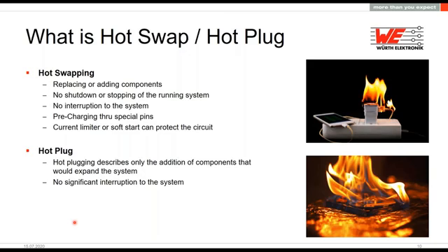So the IC also uses this hot swap or hot plug functionality to check if the system is ready to handle this high current. So it's a little bit of a provocation here with this picture, but it shows that you need this functionality to have a safe operation.